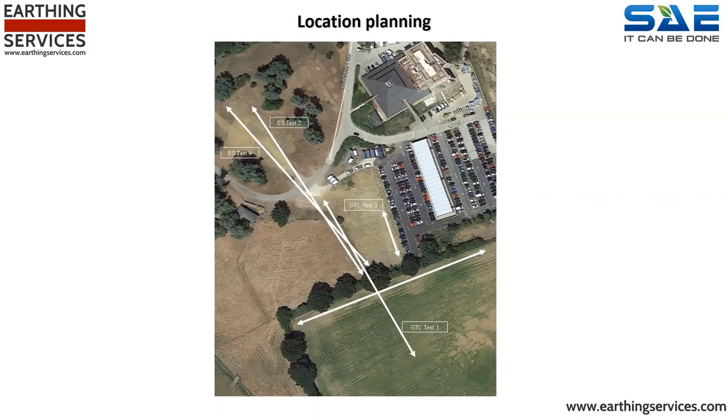A single run or collection of soil resistivity data requires approximately 170 meters of uninterrupted open land, soil type ground mass. This enables the engineers to assess the electrical resistivity attributes of the ground to a depth of over 50 meters. It is usual that the lower the depths, the more stable and generally better the electrical resistivity performance. In the event that less land is available, it is not uncommon to do shorter and therefore shallower soil resistivity surveys. However, this results in a less exhaustive data set.